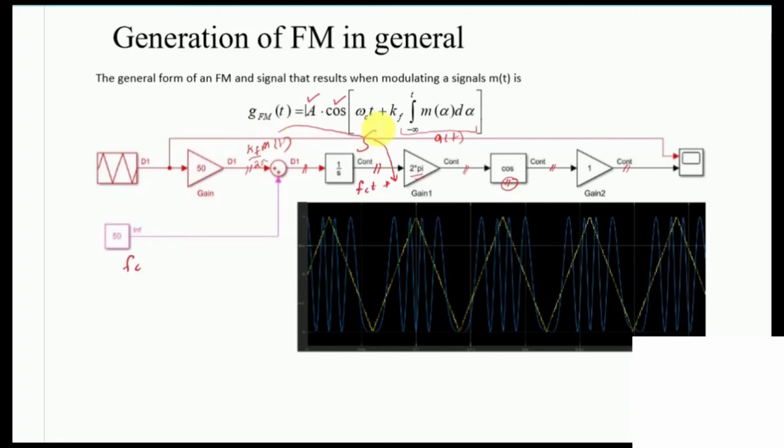So this is a generic model for the frequency modulation. Note that we can consider all of this, anything above the message signal, as a voltage control oscillator. So a voltage control oscillator is nothing but a frequency modulator. Based on the amplitude value of the incoming message signal, the instantaneous frequency is adjusted, right? So this whole thing is the direct method, that is, using the VCO, right?